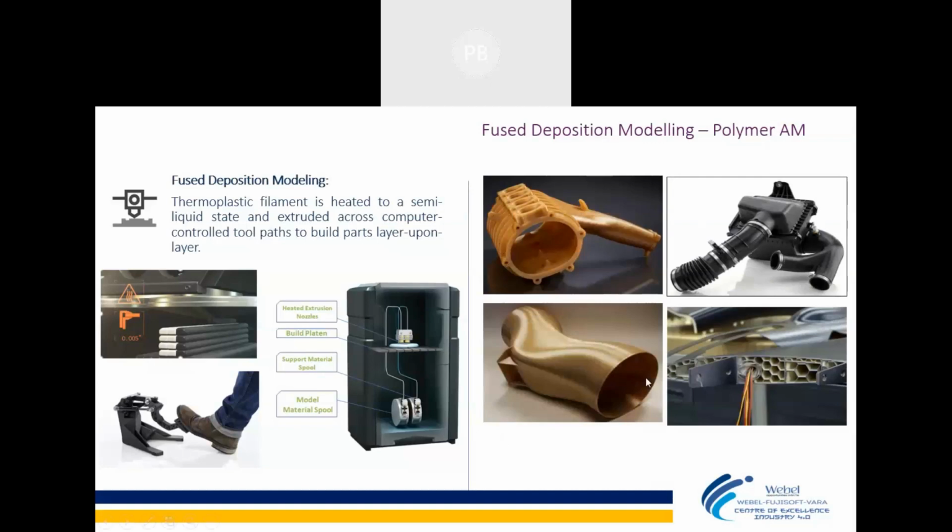These are certain parts which have already been developed and used in the industry. This is something under automotive manifolds, which can be directly put in. These are automotive hose pipes. These are parts of aerospace. Some with different infill density and honeycomb structures, we can directly print with FDM. So fused deposition modeling is one of the well-known and established technologies, more commonly used worldwide.